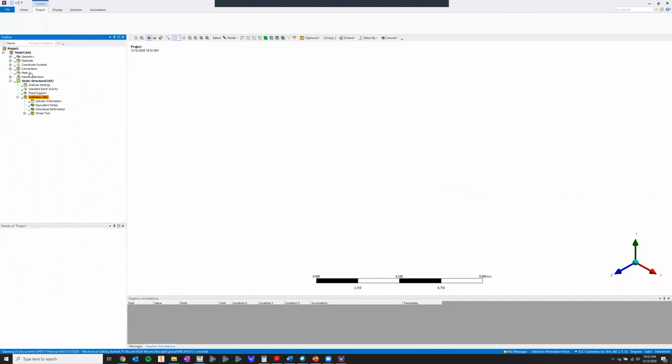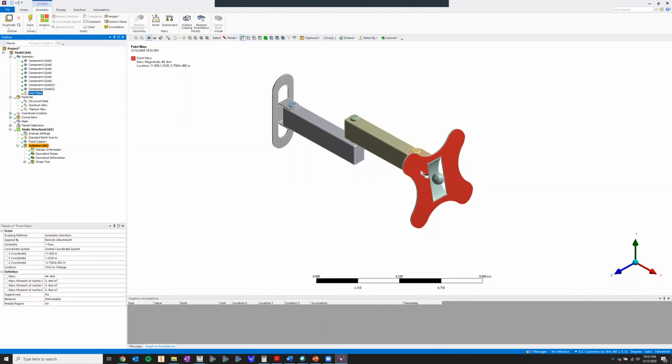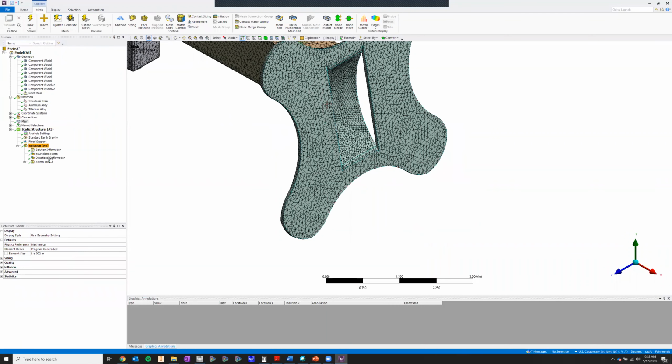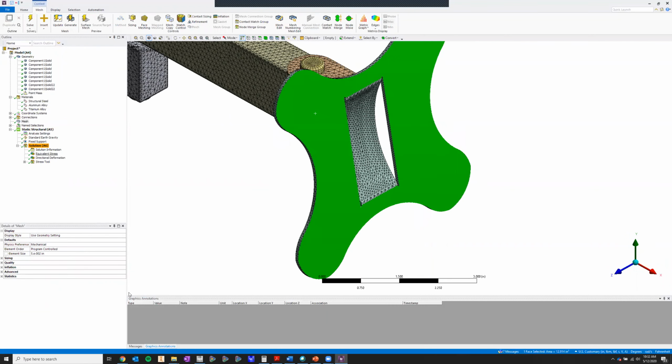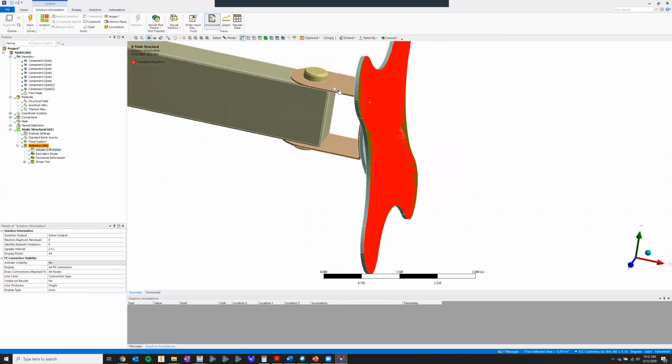The point mass is being applied to this face. So let me go back to this point mass. When I created this point mass on this face, after I create my mesh, I have all these nodes. And my point mass is applied to those nodes, as you can see here. I didn't show this earlier. I was scared that all these red lines would confuse you.